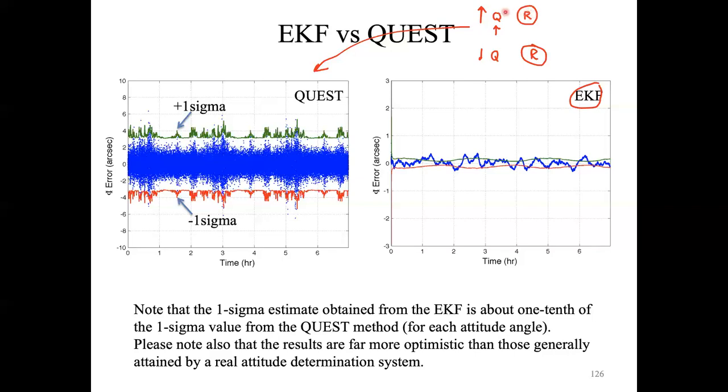The problem here is that the process noise that we have introduced varies over time, and it is possible that propagating the error due to the gyroscope is not really close to what is happening in reality. So usually reinitializing the software or the Kalman filter at a certain time enables a much more stable solution. But this is something that you can fully understand by running a realistic case. If we see that only from a theoretical point of view, you can face some difficulties in understanding fully what we mean here.